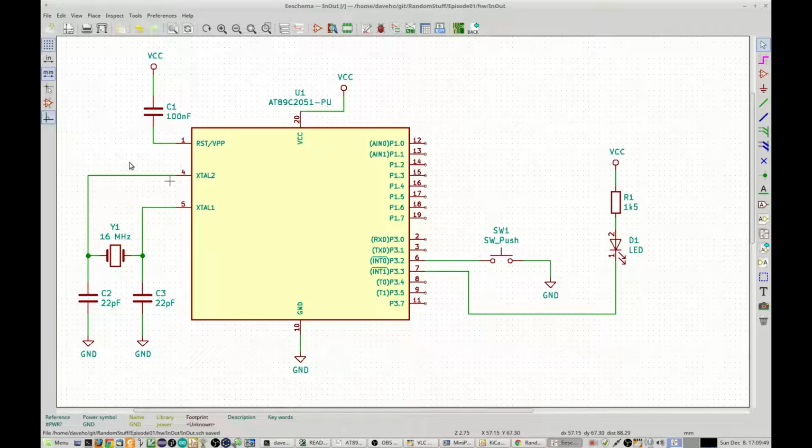All right, so for our last experiment, I'm going to try doing both digital input and digital output. And obviously, doing both input and output is important if you have an application that requires both. So far, we've only done output. And my input device is going to be very simple. It's just going to be a push button switch, which when pressed is going to connect port 3 pin 2 to ground, and essentially I should be able to detect whether there is a 1 or a 0 here based on whether or not this switch is pushed.